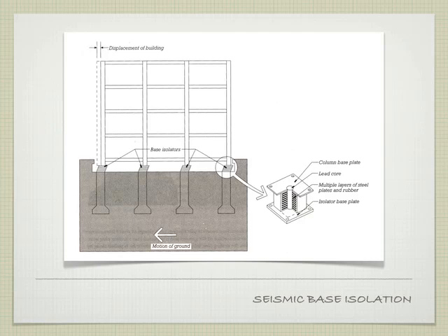Okay. The thing about it is, since it's built right on top of the fault, right? If an earthquake were to hit, this particular building would get a big jolt at once rather than a rolling, undulating earthquake that would be once the earthquake spreads out, right? So if they could take the building, right, and allow the building to absorb as a unit that one big jolt, right, the building could actually stay intact rather than crumbling into a bunch of pieces, right? So what they did is they dug down under the building, right, poured an entirely new foundation, right?